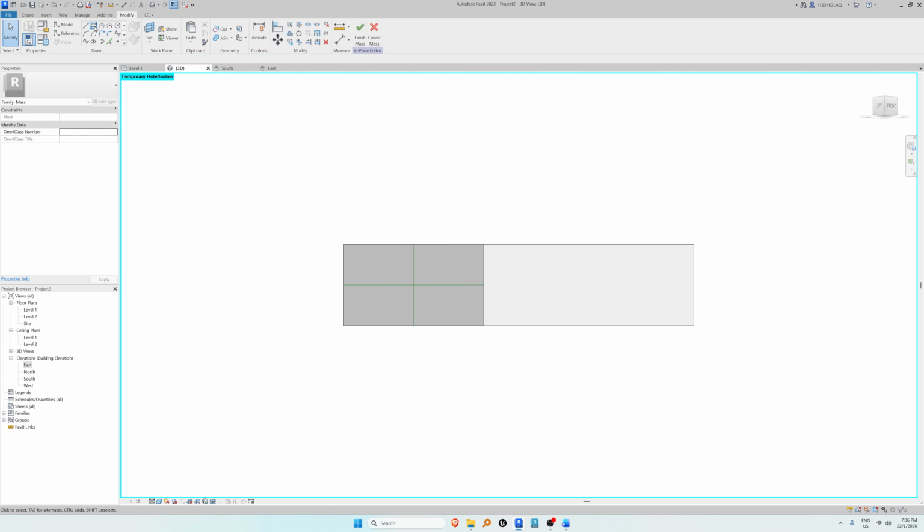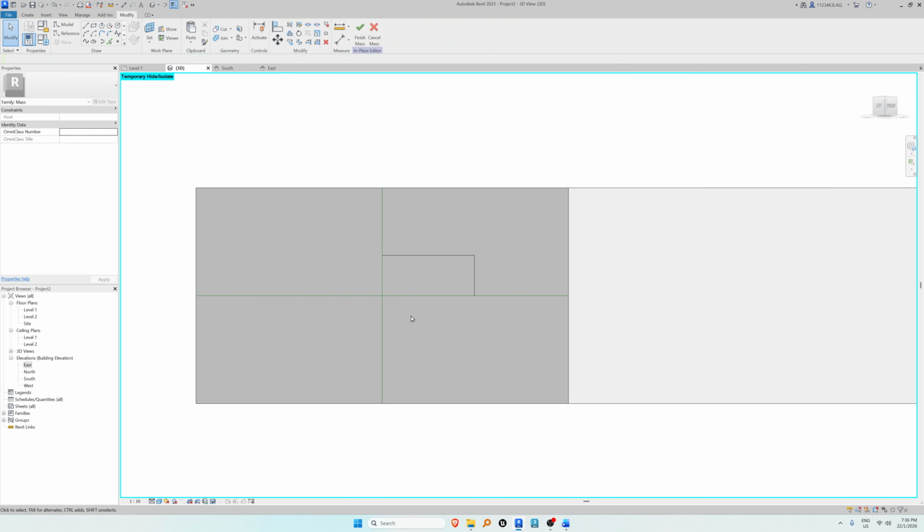Okay, we can delete them, no need to make them invisible. Let's delete them after. So maybe we have something like this. That's 15 by 40. Maybe 15 by 35. Okay. So this one, let's delete the base of this rectangle. So delete this one. Let's delete this side. Press tab until you can find it. So pick this, mirror this, select these lines, hold Control, select the lines, and then mirror them back down.